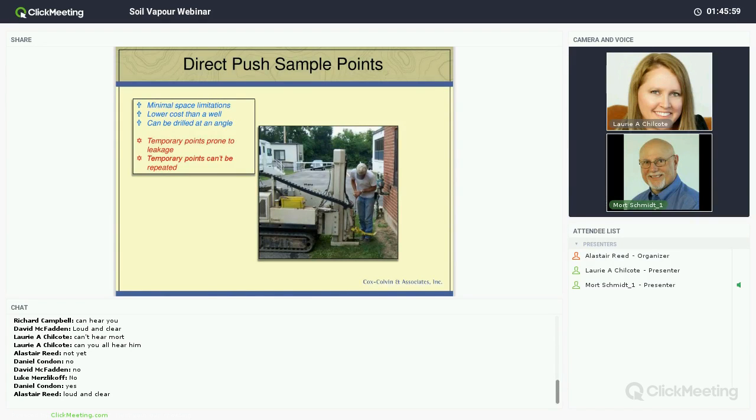So how do we collect soil gas? Well, we collect soil gas. It's typically broken into two different areas. One is exterior soil gas, deep soil gas, used synonymously, under a depth of 5 feet. And this is a direct push rig. Geoprobe is a brand name. And they advance the drill rod to a depth of 5 feet or more, connect tubing to the bottom, and